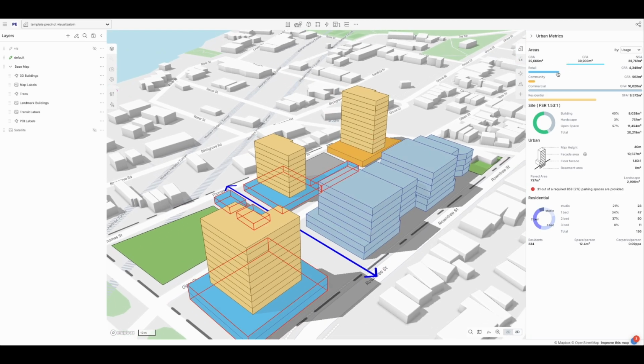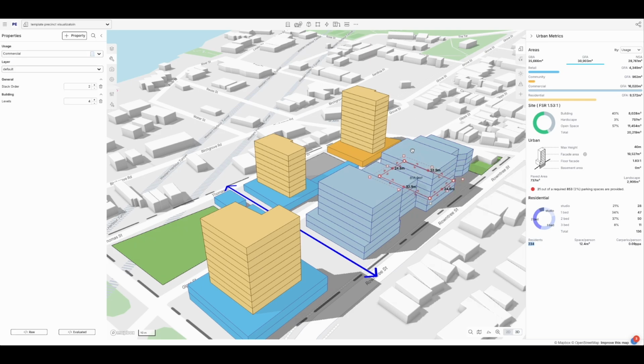And this is enough to get the areas. We're modeling out the dwellings, the number of residents, the paved area, the number of car parks required. We can easily get the number of jobs modeled out by getting the areas of the commercial, which is 16,000 square meters of commercial GFA. So if there's a worker every 10 square meters, it's 1,600 workers.